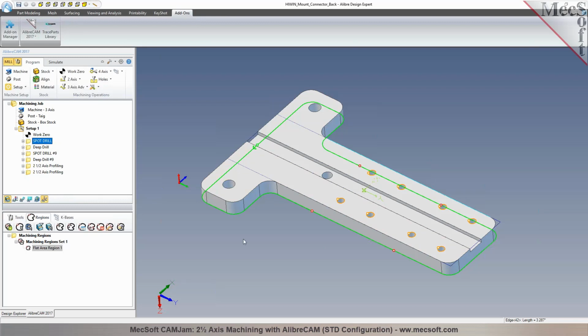If you just resize the sketch, and you're using a sketch as your containment or a region for machining, then you don't even have to repick it. If you add or drop or modify the sketch, then you'd have to go back and reselect it. So that's the beauty of being able to work inside an integrated system, is you don't have to re-export and start all over again. Also, this entire operations workflow that you created, you can save it to a knowledge base.